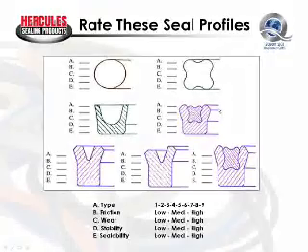This seal, however, over here is a square profile seal. Height and the cross-section are the same. The type of seal is probably about an 8, very high up on our continuum, giving us high friction, high wear. Stability, though, is basically only medium. So our sealability isn't going to be as high as it might be because of the relative instability of the seal profile.